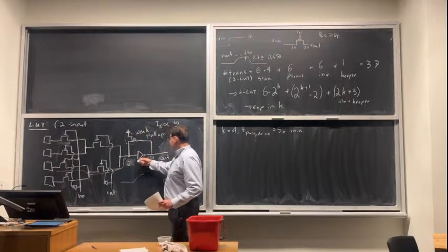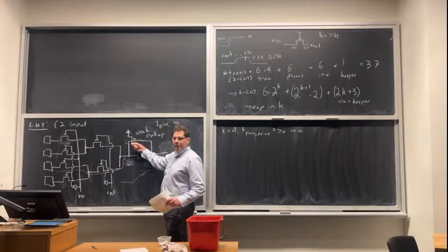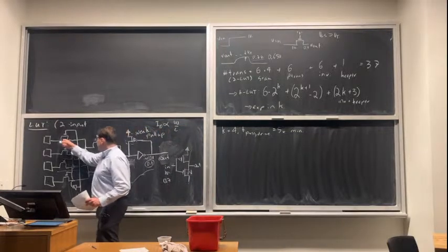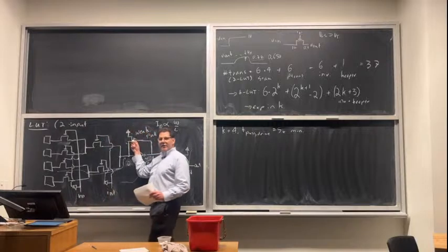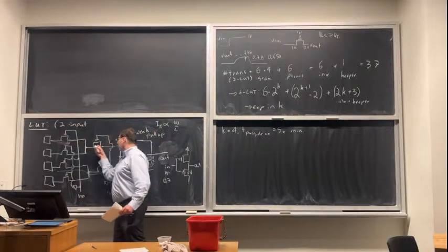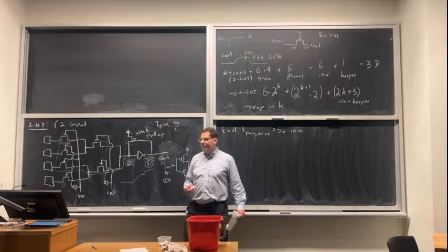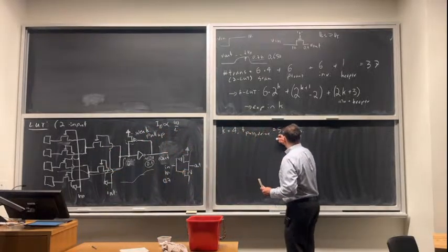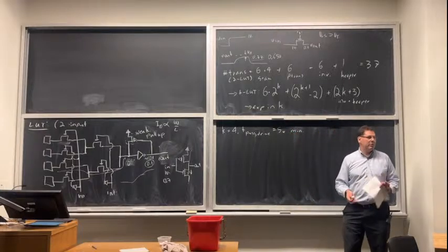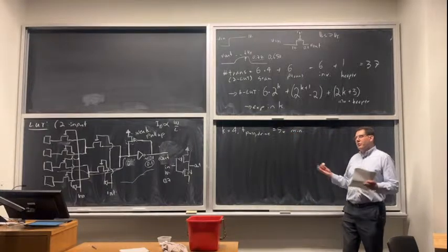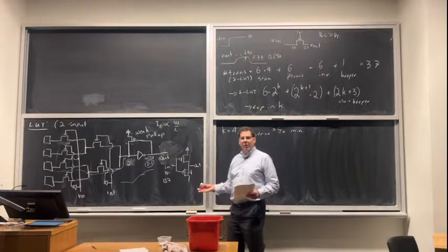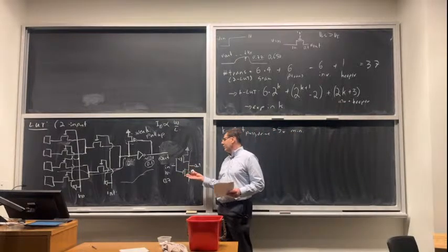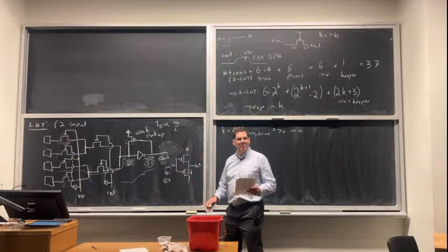This first inverter I want to be pretty small. This I want to be very small. So what's left? These pass transistors, I need them to be stronger than this, and how strong they are also impacts my speed. So it's worth spending some area on them. So I'm going to decide that I want them to be 5 times the minimum drive strength, which is like a reasonable number. If you were doing this, you would actually go spice this or use a tool that knows how to spice this kind of circuitry. But I'm telling you 5 times minimum drive strength is reasonable.